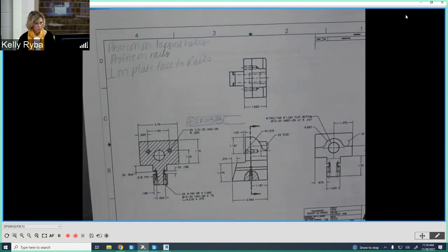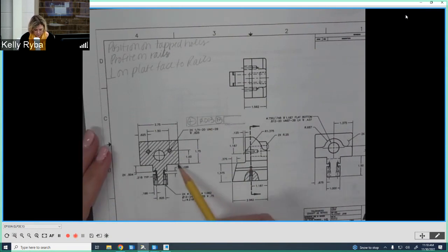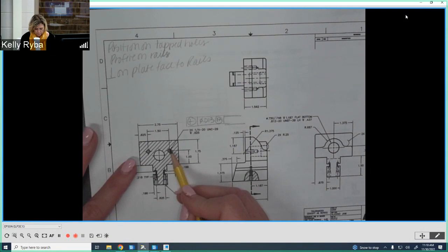and then we'll just devise our scheme for our datums. So we have to look, where is this being dimensioned from? And so you'll notice here that we're dimensioning from the bottom here up for that location of that hole. That does need to be 1 inch, does it? Because I'm looking at it where it's riding on. So yeah, that needs to be 1 inch. It's here.